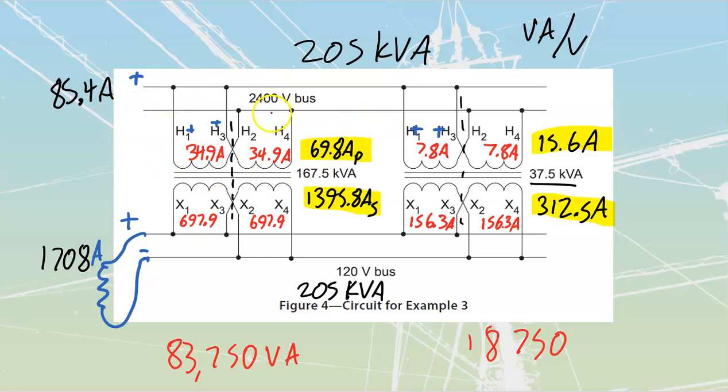They don't show it inside here, but in most cases, I'm going to have that disconnect in the primary, which means that if I'm putting in a disconnect, make it a fusible disconnect. Stick the fuses inside of it, and it just eliminates one more piece of gear that you would need to have on the low side. Let's take a look at these currents that we have over here, and let's find out what this transformer setup would do underneath a fault.